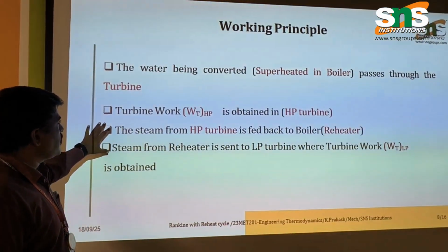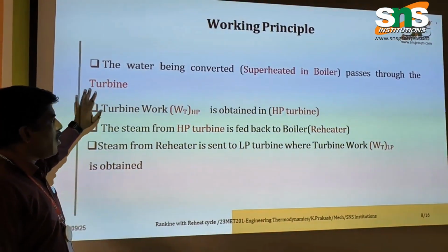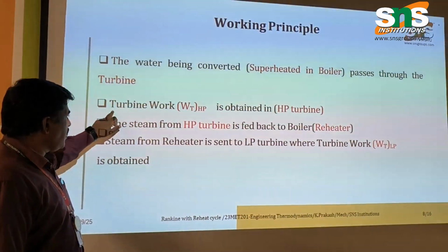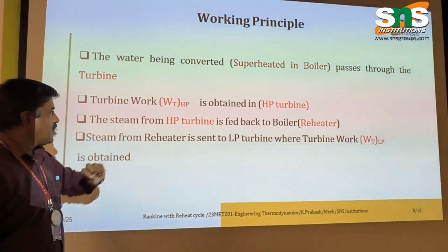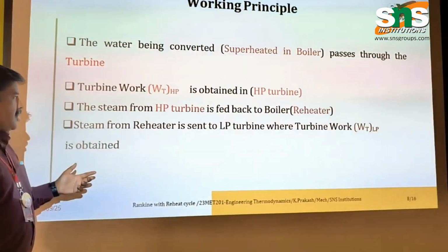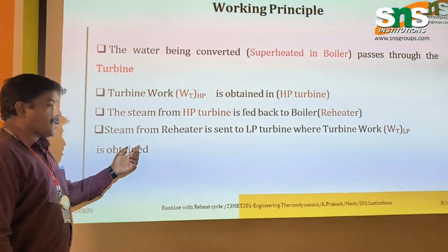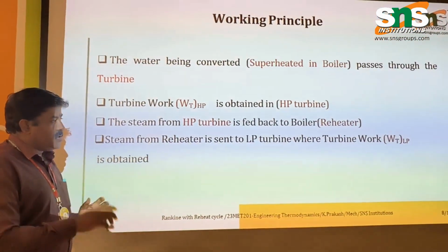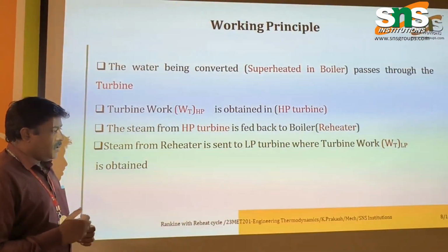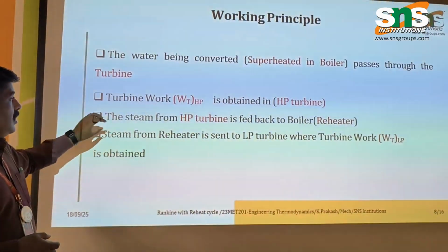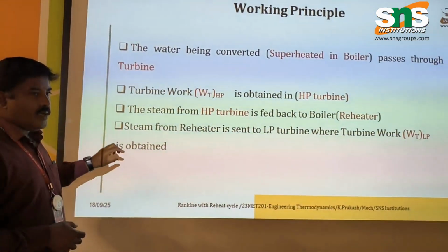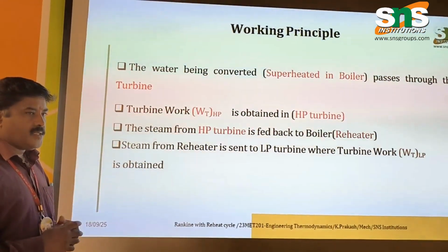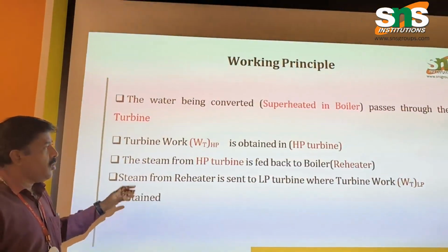The working principle is that the water is converted into superheated steam. Turbine work is obtained in the high pressure turbine and also in the low pressure turbine, so work is extracted in two places. This plays an important role in the expansion of the steam, and the work is improved so that thermal efficiency is increased. This is the working principle.